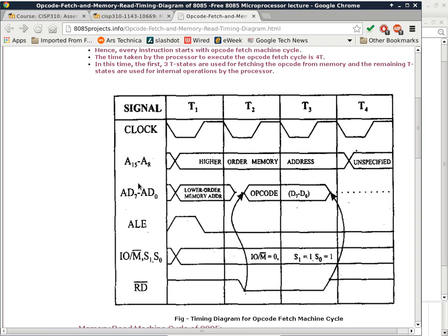Because a processor, maybe half of the pins are ground. But many of those are grounds because you need to ensure a good ground connection. But still, even if half are grounds, you still end up with 500-plus pins that have to go somewhere else on the circuit board. Okay, the memory chips each have 240 pins.